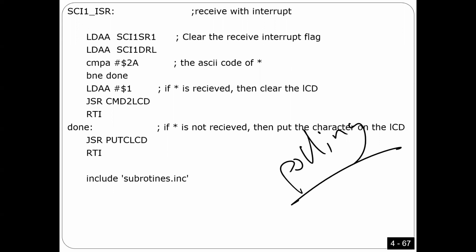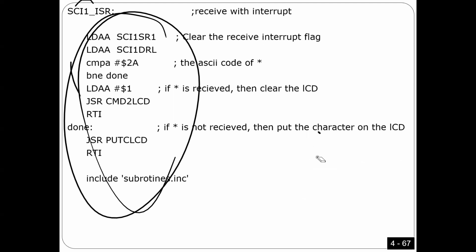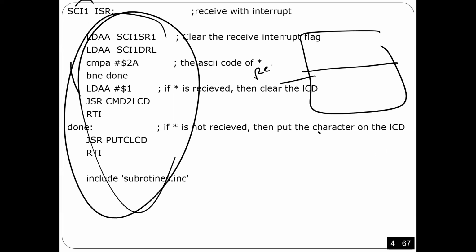That means once the receiver receives a byte, it's going to interrupt me, right? So when you have an interrupt here, what does it mean? Simply, it means the receiver received a byte, go ahead and take it, right? So where I have to take it, I'm going to tell you how and where, because I told you we have here a receiver part.